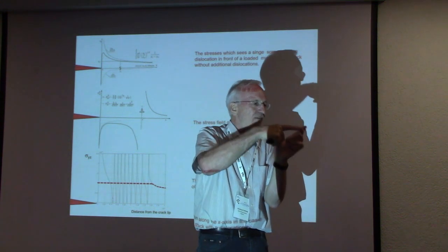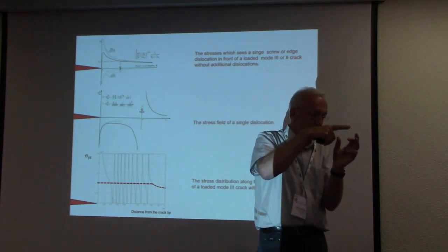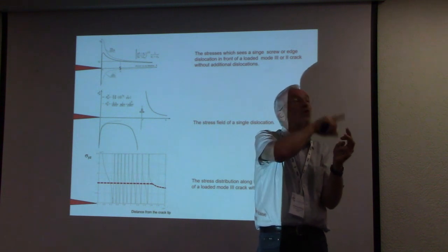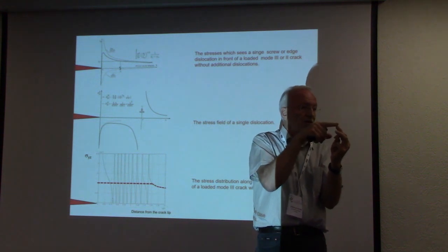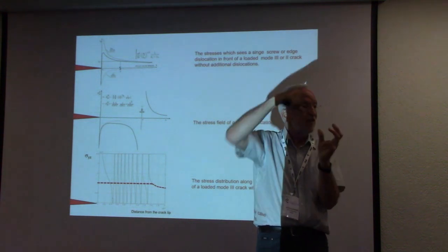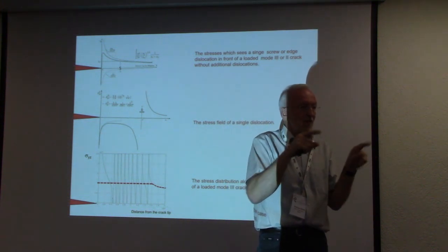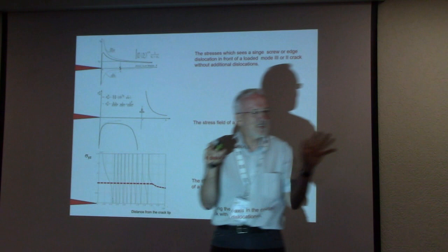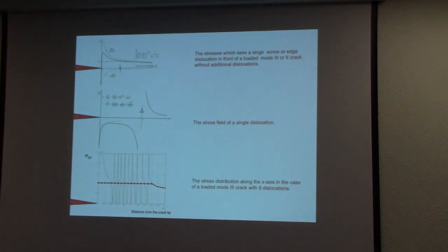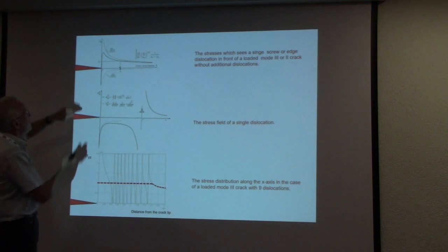And the only thing you have to do when you calculate is, you simply look at the position of the dislocation, you look at what is the stress caused from the external loading, and what is the stress from all the other dislocations, all the other pieces of dislocations. And then you know if the dislocation can move or cannot move. That's all. So in principle, the calculation is simple, but it is simply a problem of power. So now here you see what happens when we load up.